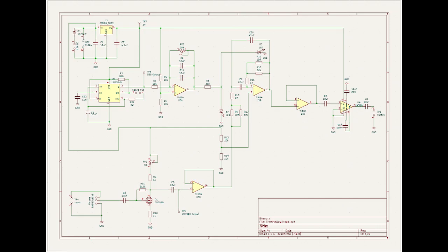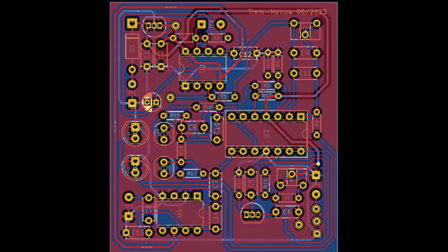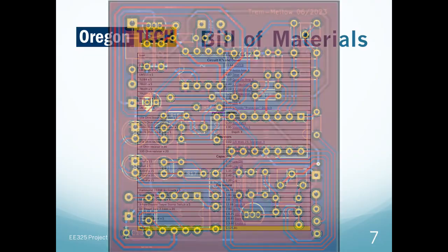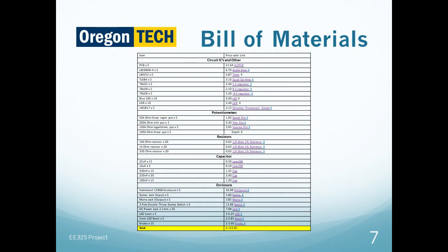Soldering the components without creating a short caused the greatest amount of difficulty. Since the board was so narrow and the amount of traces was high, it raised the skill required in assembling the pedal. The printed circuit board and Hammond enclosure were the 2 most expensive items in our project. Failure of a discrete, soldered component is not physically easy to replace but is financially inconsequential. Choosing an enclosure with greater width and thereby a wider circuit board would have permitted larger gaps between the traces.